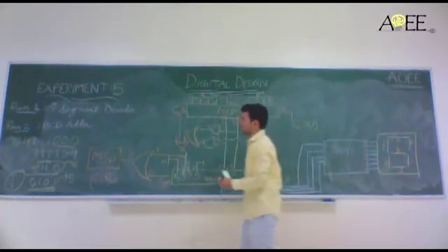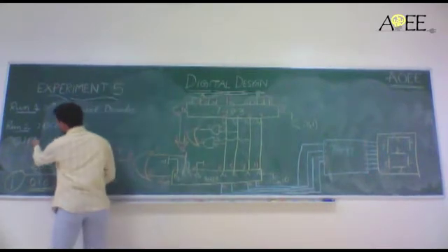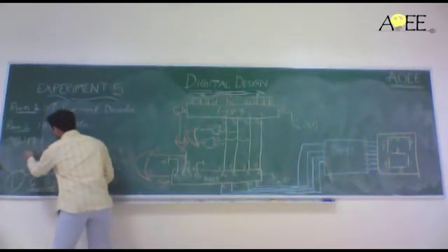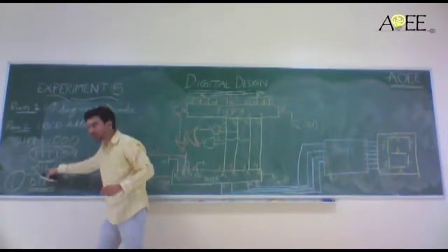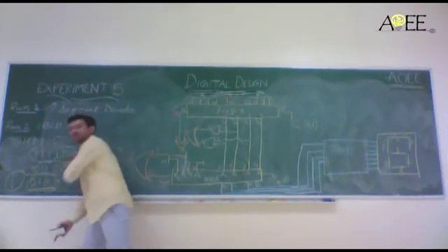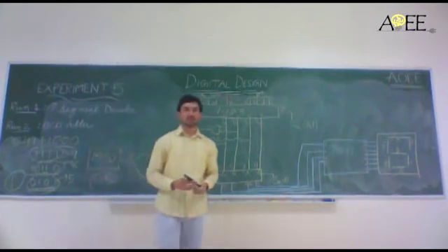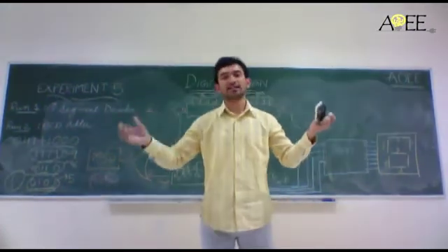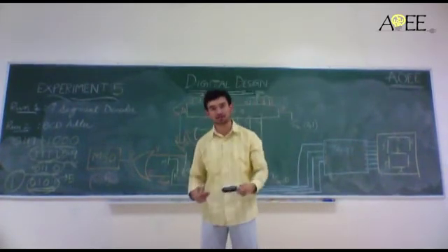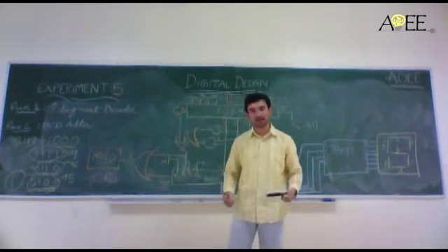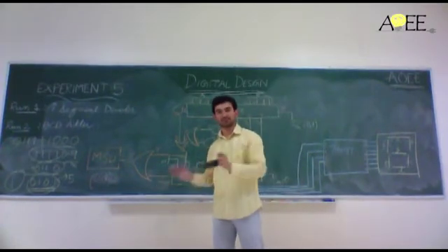Two numbers were initially added, the sum was checked. If it is greater than 9, then add 6 to it, find the answer and display. Logic is add two numbers, see if the sum is greater than 9. If it is greater than 9, add 6 to it, otherwise leave it as it is and then display it.